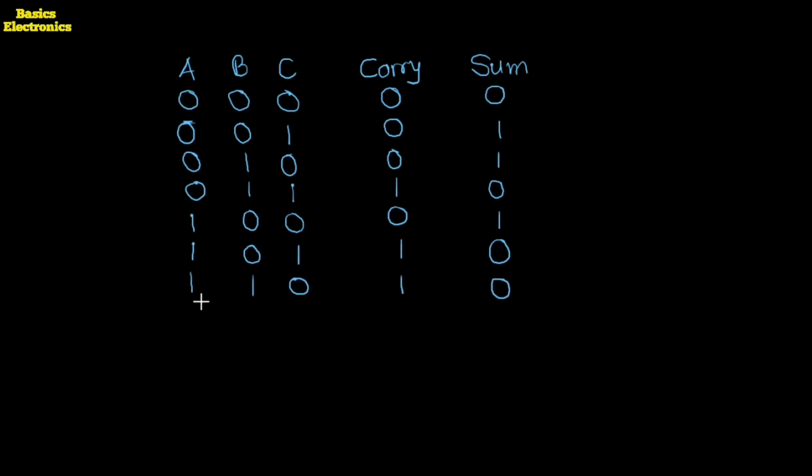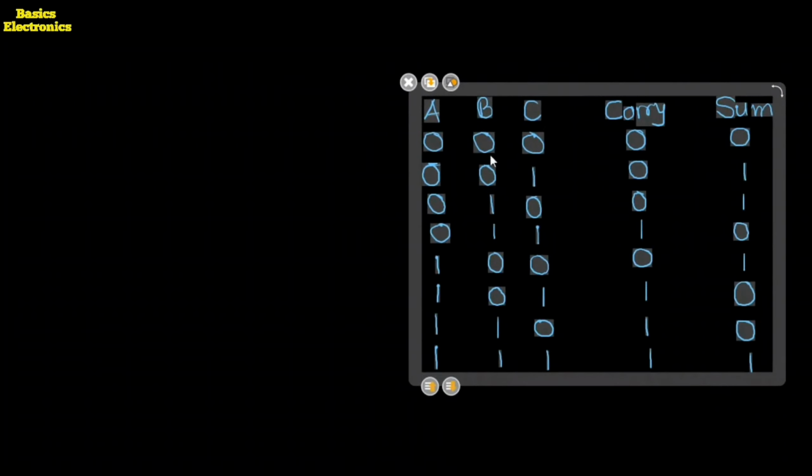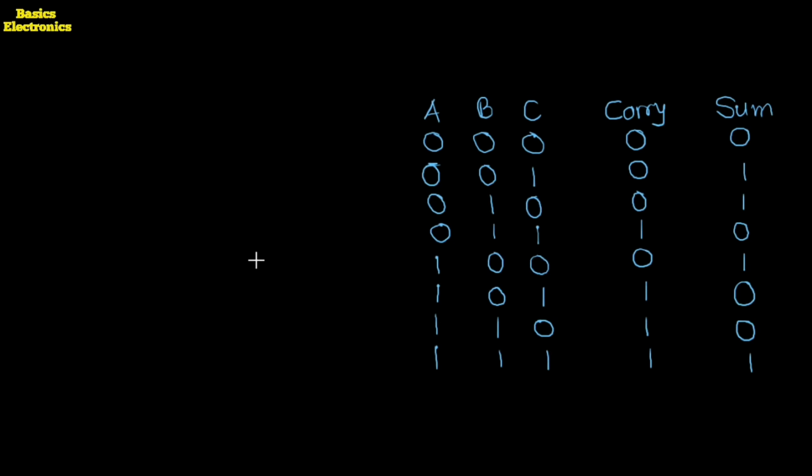Then the next combination is all inputs 1 1 1, the example which we had seen along with its outputs. Okay, so here we get carry equals 1 and sum also equals 1. So here you have to draw this table after the working of the full adder. Now we will see again the writing sequence for this full adder using the gates, or we can say using three AND gates, one 3 input XOR gate and one 3 input OR gate.